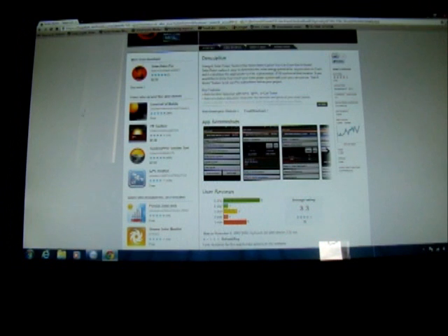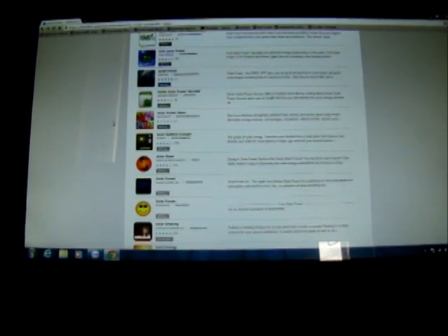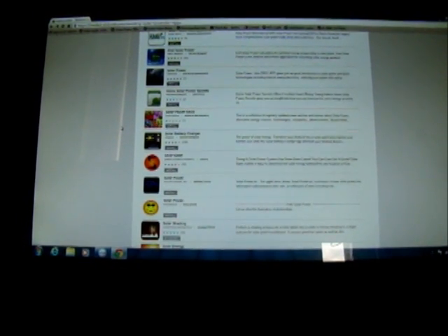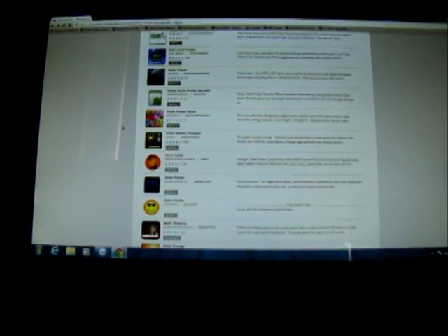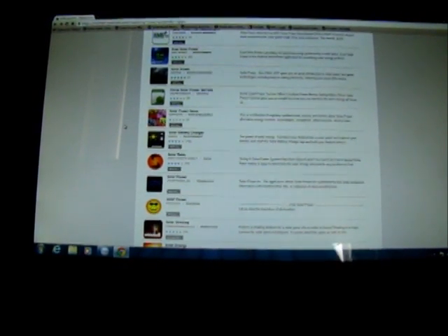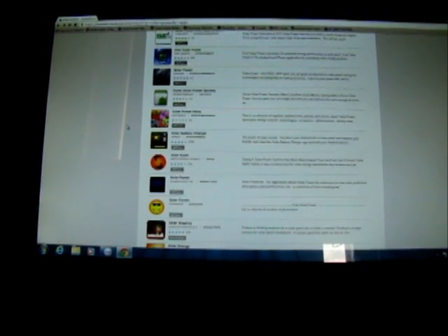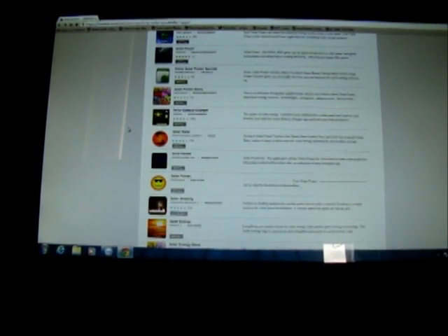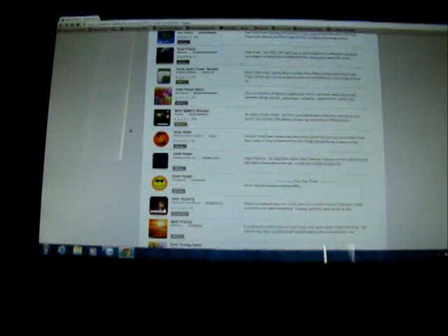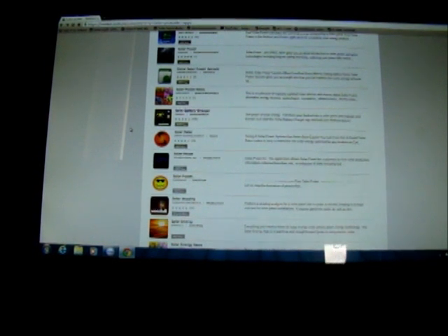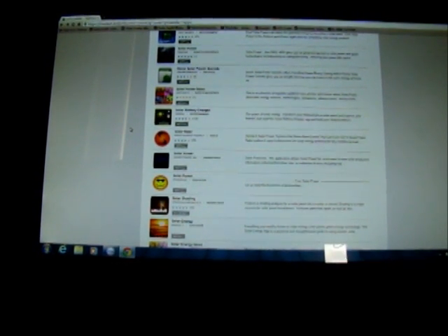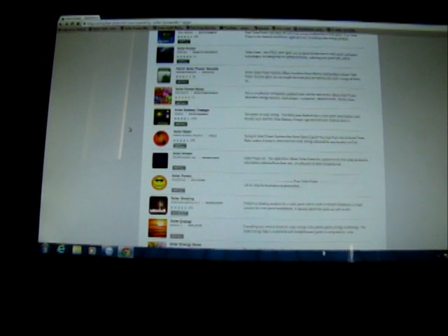a shading app. From last time, when we do BIPV or on-grid solar power, like for example right now it's very hot, the FIT, feed-in tariff, one of the tools you must have is always the Pathfinder. You want to figure out the shade, like the tree or the building blocking your PV. Last time we needed to climb up to the roof, use the Pathfinder, draw a graph, then bring it back to the office and put it in the computer to do the calculation. Oh, those are very tedious.